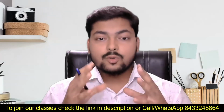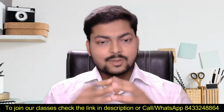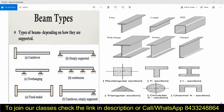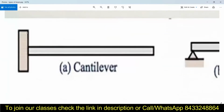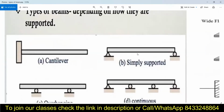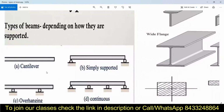Now, what is that? We have differentiated the beams on the basis of the supports. So let's see that. Here you can see beams depending upon how they are supported. If a beam is supported like this, then it will be known as cantilever beam. That means we have the support on one side and the whole beam is hanging. So this will be a cantilever beam. If it is supported on both sides, and that too one end is simply supported, the other one is roller support, then that is a simply supported beam.